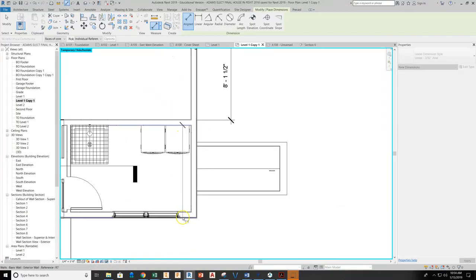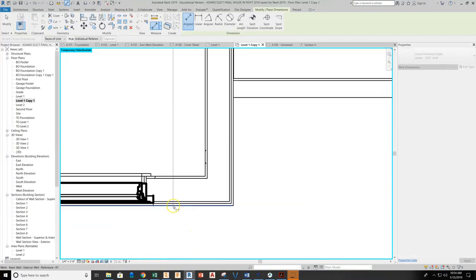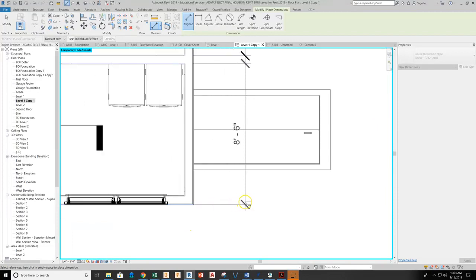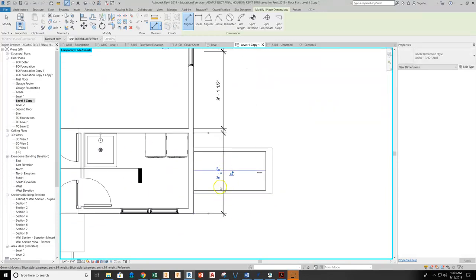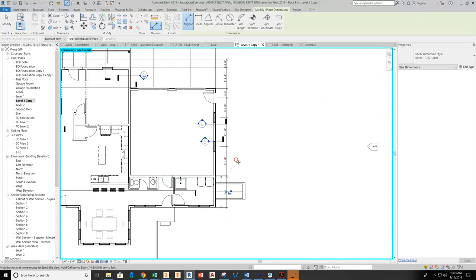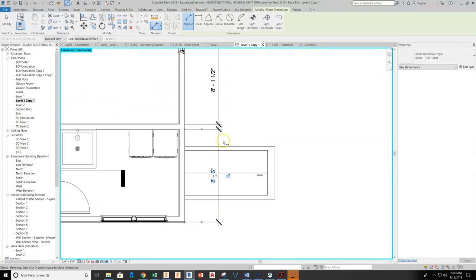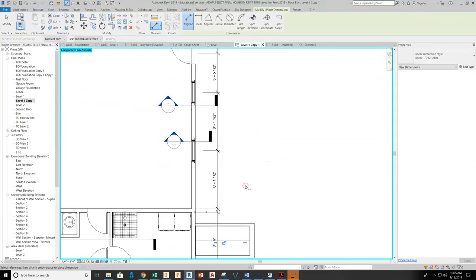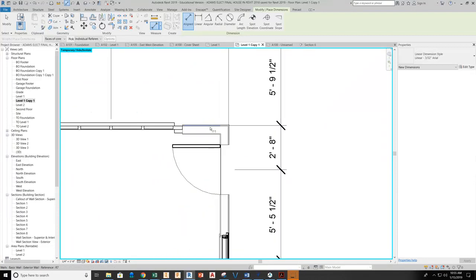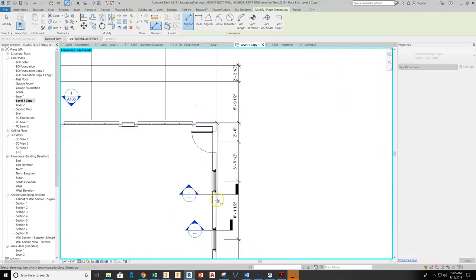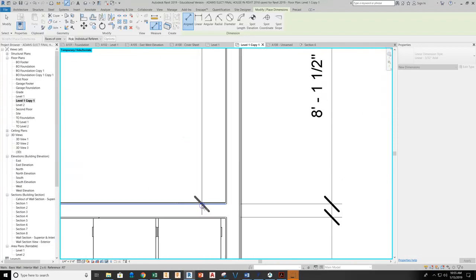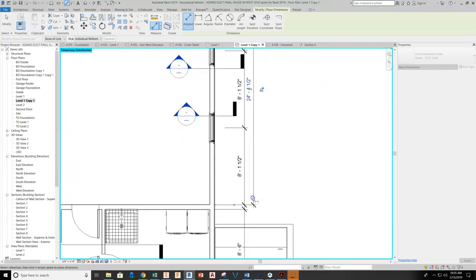And then I'm going to go ahead and grab this room size, this time going to the outside of the sheeting on the corner. Now, as I come out, I'm going to be actually sitting over top of this Bilco. If it's clean and I can read everything, I would keep it. If not, I would pull out further to miss that feature on the structure. The Bilco would have been dimensioned on the foundation, so it's not really truly necessary to put dimensions on the Bilco. I am going to come back, however, and I'm going to pull dimensions for the overall depth of the garage, knowing how deep the full garage is, and pull that out to this point.